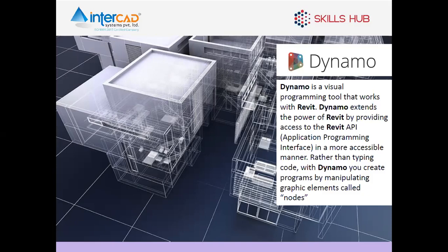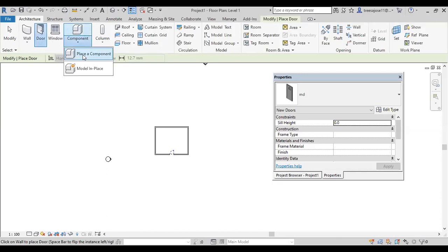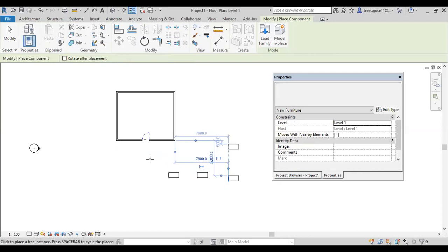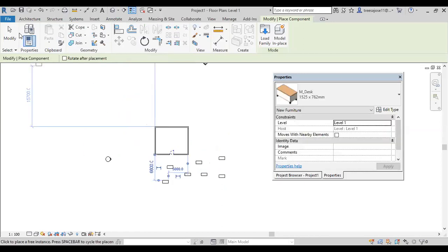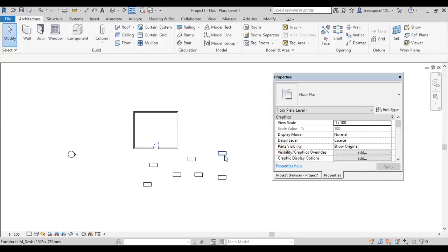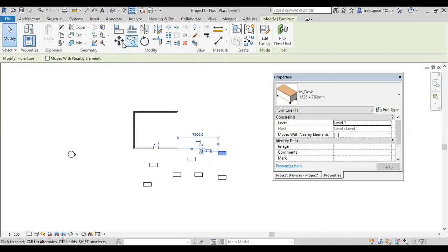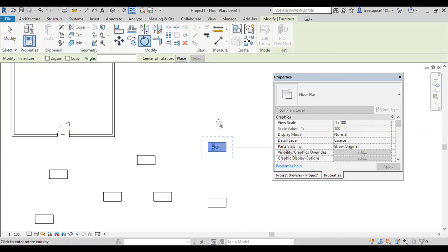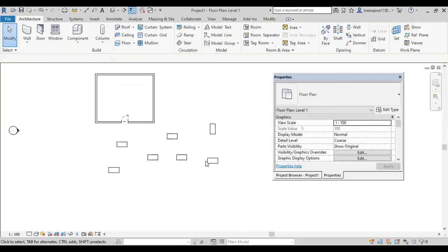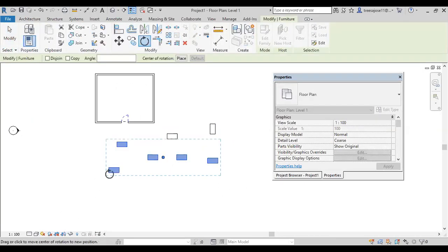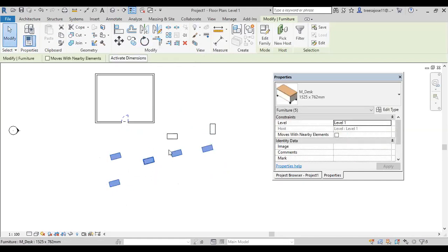and all. For example, maybe we have some structures placed, and after that, we may feel that we have to change the orientation. That time, the only procedure is you select that one, then go to the rotate command, then pick the base, whatever may be, then rotate it. We cannot rotate this in one single step. Because if you select the entire table and go to rotation, it is possible, but if I put the base like this, then the entire table will be rotated like this. We have to maintain the base. That time Dynamo will help us a lot.